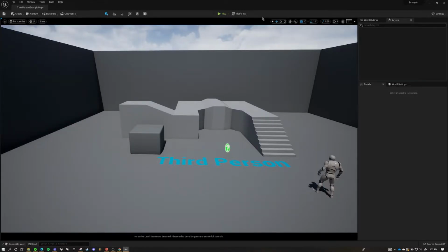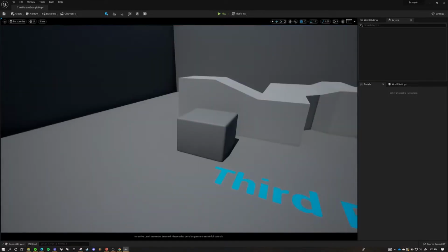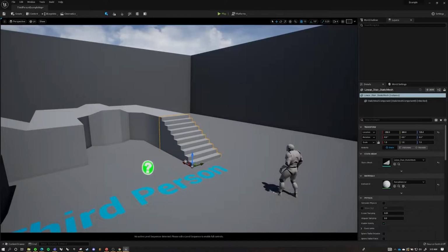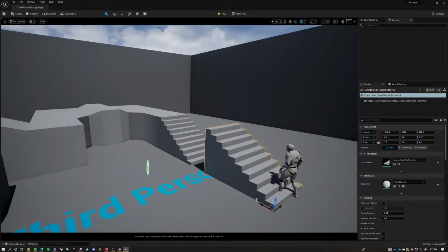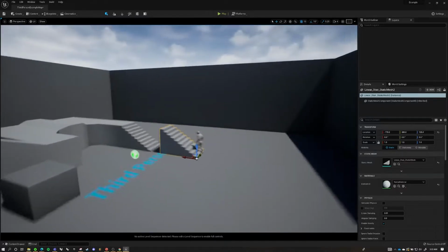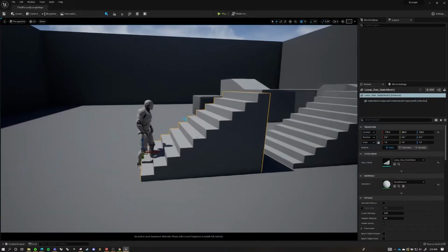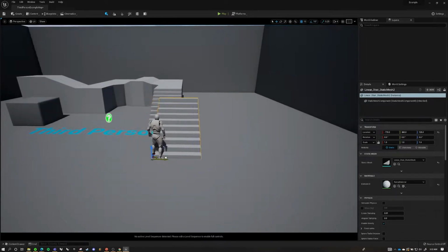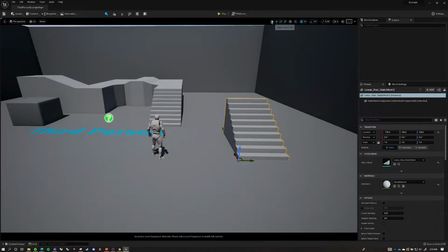Moving on to the other side of the screen, there are some more familiar tools. This is basically your gumball control and OSnap settings. Let's focus on this staircase. Right now I have the Move tool selected, which will display a gumball with arrows just like Rhino. Holding and dragging an arrow will move it. And holding Alt will keep the original, also just like Rhino. These 4 buttons are a selection tool, move tool, rotate tool, and scale tool. I'll demonstrate how each one works. It's pretty straightforward.